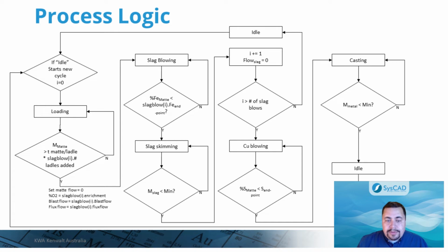Although the overall sulfur content decreases, this is really the effect of increasing proportion of fixed sulfur concentration blistered copper and depleting of matte. Depending on the temperature and oxygen solubility, the sulfur solubility in blistered copper is around 1 weight% of sulfur. In this example, the copper blowing endpoint was set to 0.5% sulfur, which triggers the end of the copper blow and starts the casting sequence.